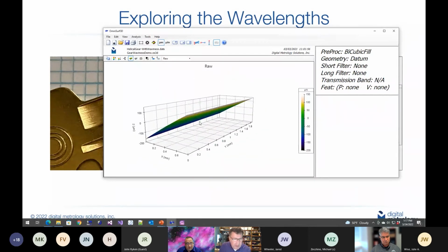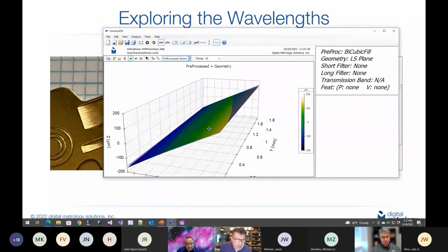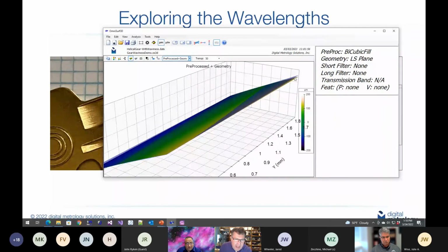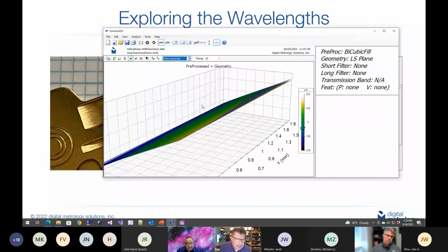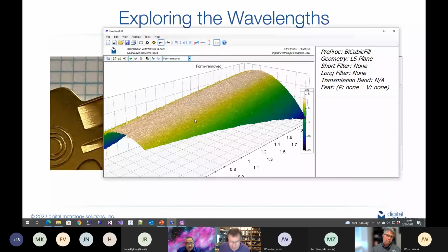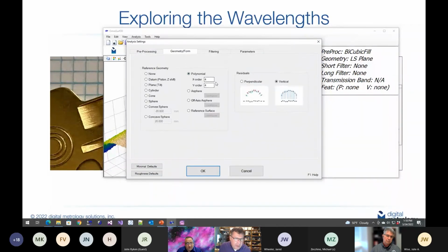It just looks tilted. But if I put a plane through my gear shape, like measured gear surface, we can start to see that the plane doesn't fit very well. See, the plane in glass is kind of diverging from the edges. And when we level that plane, we still have a lot of error left over. So one of the most common tools people will do is they'll jump to a fourth order polynomial.